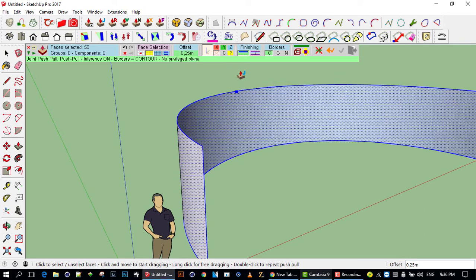But interesting, you'll notice that here by finish, it defaults to this first setting, which if I pull now, I'm going to pull the face and then leave the back face empty. So if I click on the thicken here, it automatically will add the plus sign. Or I could just hover here and press the control key, and you see what happens here. It shifts over to thicken immediately. If I press control again, it shifts back over there.